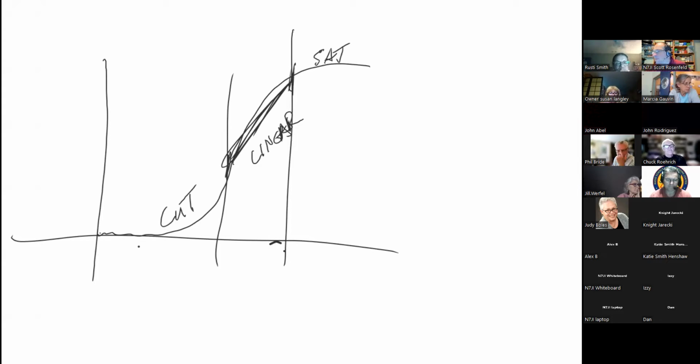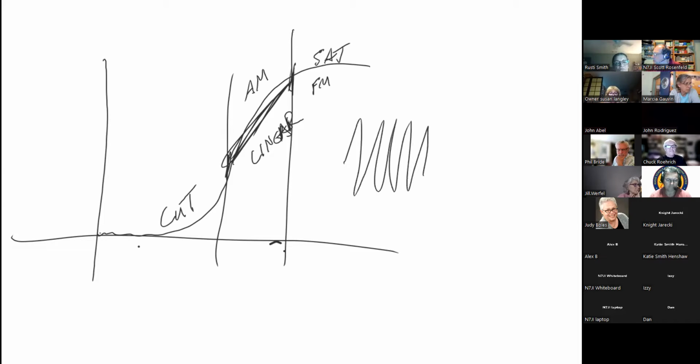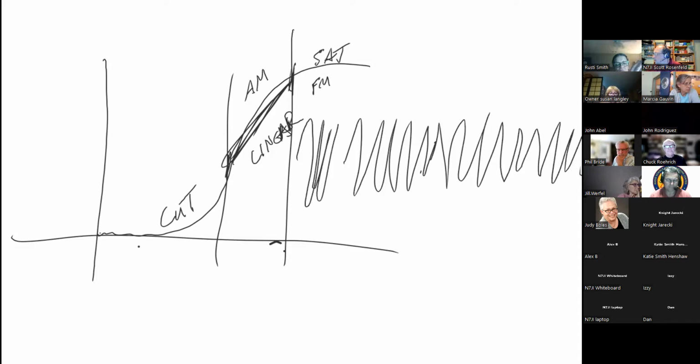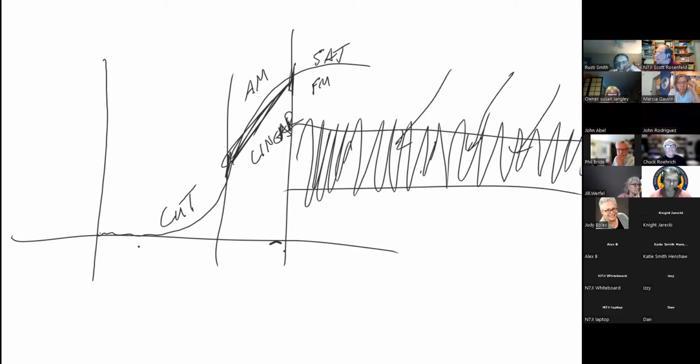An FM amplifier doesn't really care, because all we're really interested in is the frequency. We go faster and slower, and we change our frequency, and then we amplify it, and then somebody cuts off the top and the bottom anyway. So it doesn't matter if it makes more or less signal. What's really important is the frequency that's contained inside.